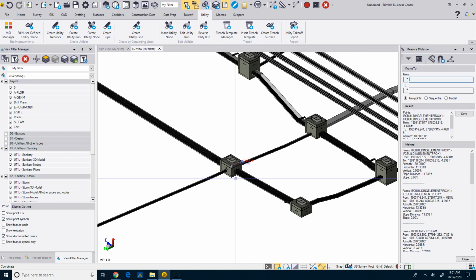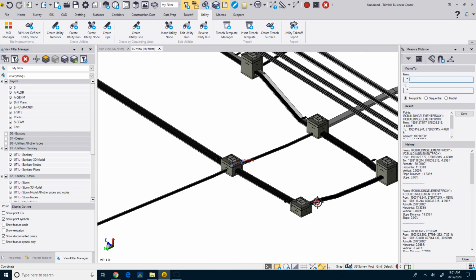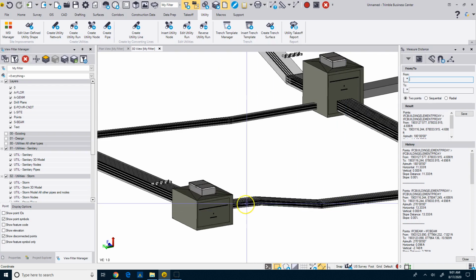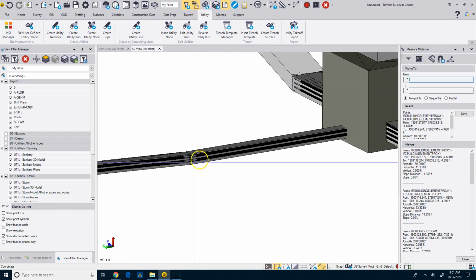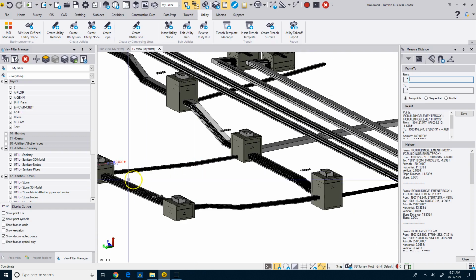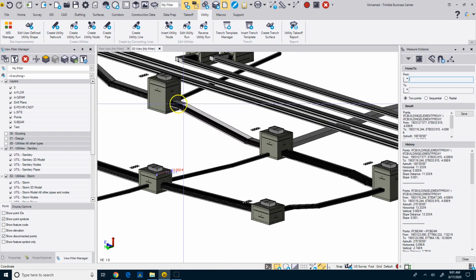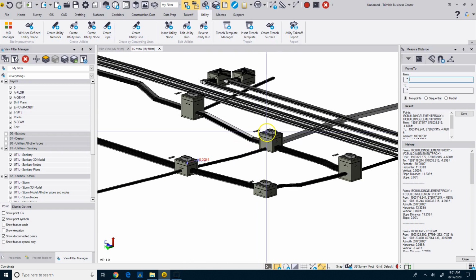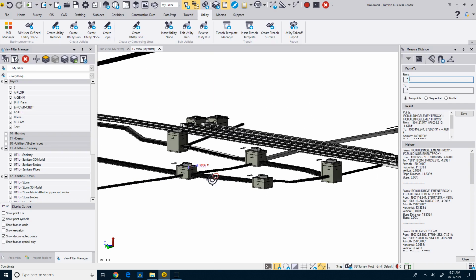to be a little bit different because what we're trying to do is make sure that we account for the different elevations of these conduits. So you can see that I have a break here. It's not a straight structure to structure run. Here you can see that it's coming down here. So these are all different elevations.